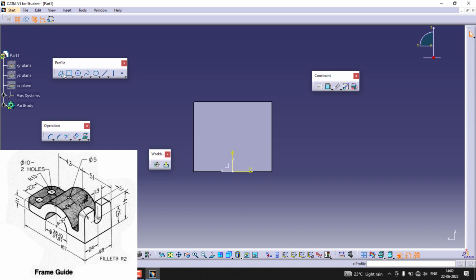Yep, so here I just need to sketch this particular cutout slot, so I'll do the same thing. For that, if the snapping is active, you can just remove it. The grid snap is there. Now you can start with this, but you cannot snap these edges in CATIA. So can you turn on the arc? 3-point arc is also there, but right now this is the better one.